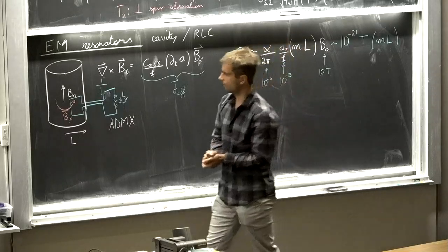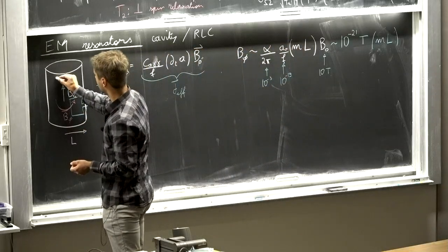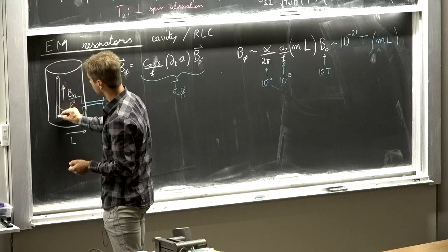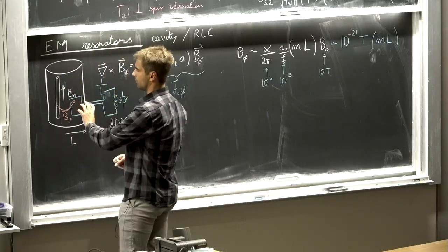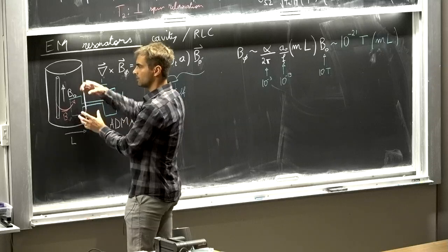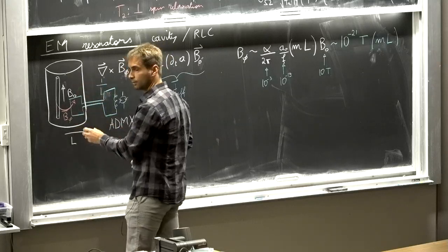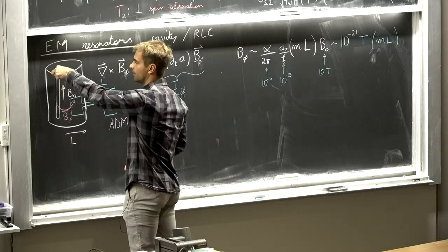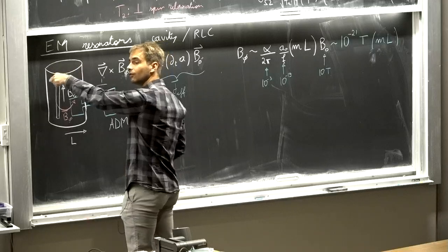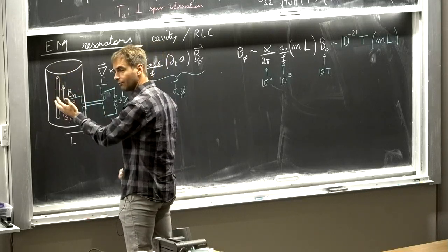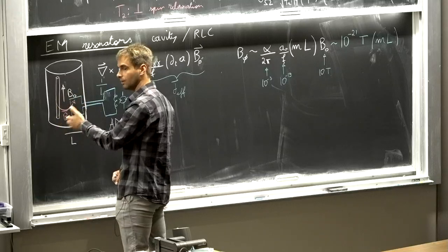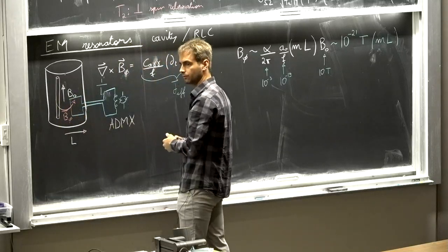What they do is they have tuning rods. Your harmonic oscillator in that system is some electromagnetic mode inside your cavity, and some conducting rod or rods inside the cavity change the functions of your cavity modes as well as the eigenvalues, which are the natural frequencies.